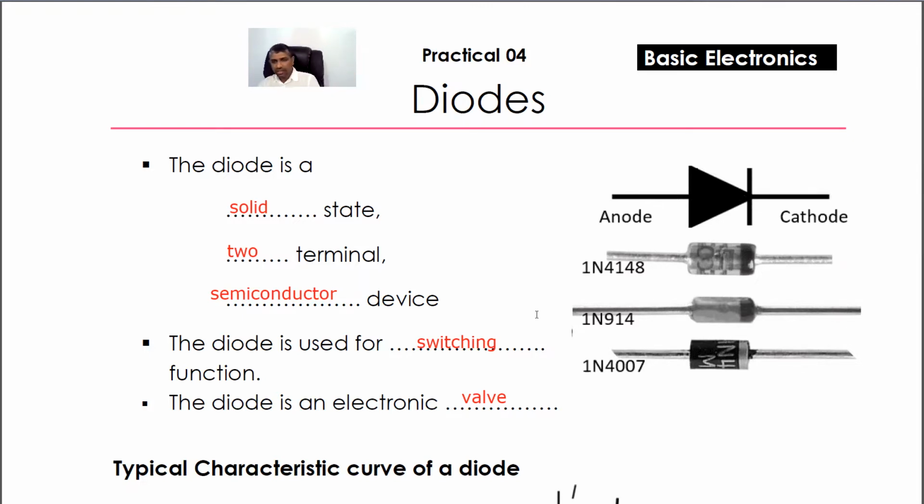In the case of a diode, when the anode potential is higher than the cathode potential, there will be a current flow in the direction of the arrowhead. This arrowhead says it is possible to flow current in this direction, but in the opposite direction, it stops.